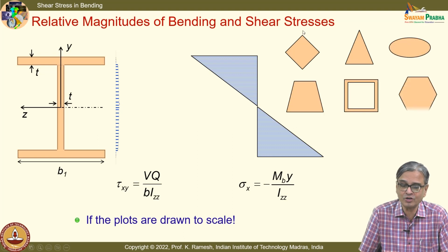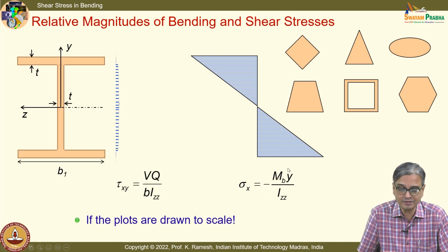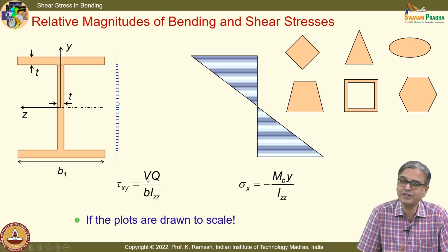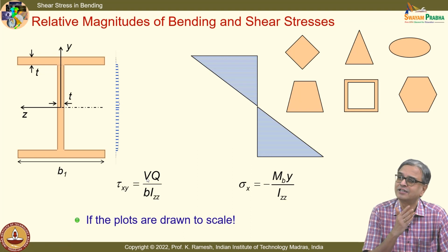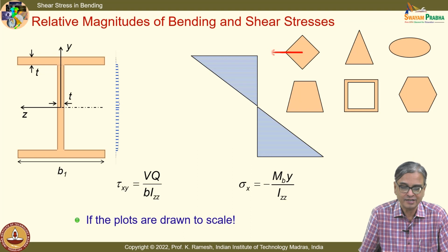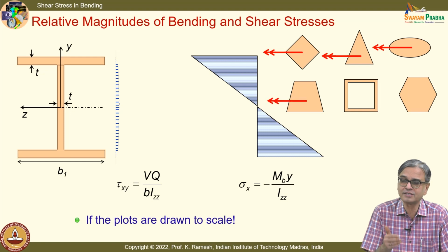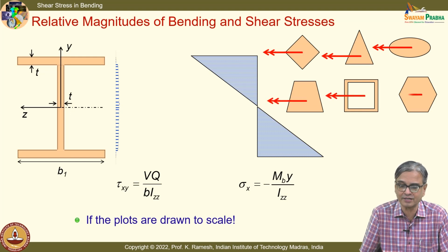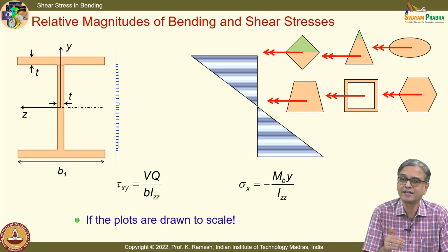the only restriction was that I should have a plane of symmetry. So, I can find the bending stress using this expression, look at the bending moment diagram, get the bending moment and simply apply it. Look at the shear force diagram, get the value of V, get the value of shear stress. You can do your design course comfortably. And for you to get the shear stress, you also have to find Q, and Q is nothing but you progressively find out what happens at each level, okay, and then plot it.